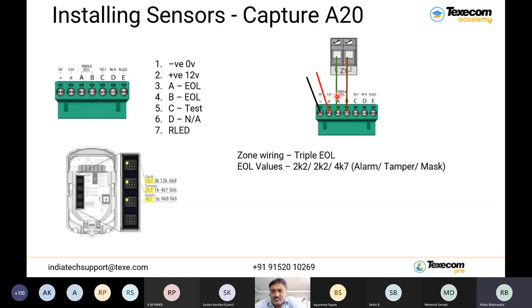And as the PIR motion takes power in order to operate, right? We have 2 types of sensors. One is non-powered devices, another is powered devices. Powered means which takes the power in order to operate. So PIR motion takes the power and you need to give the power from control panel. In the control panel, we have aux positive and negative and connect the wire over there. So this is the simple connection you need to do.